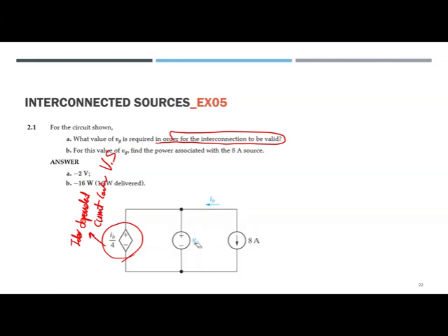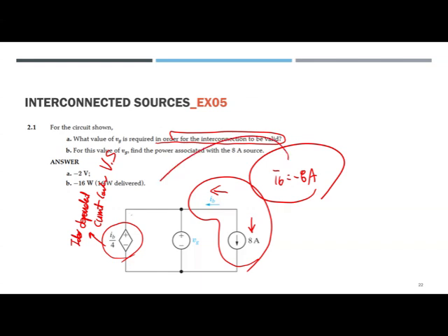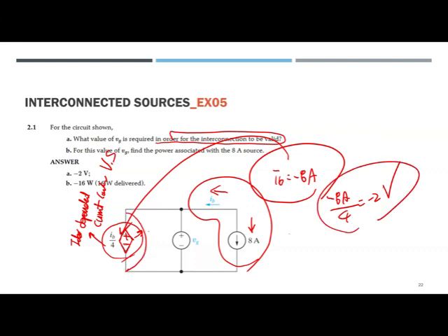Step one, that was the reverse direction. So I sub B right here is minus I sub A, and that was plugged in here. Oh, I'm sorry, minus the 2 voltage, because that was the ideal dependent voltage source. So this is minus the 2 volts, and that was also minus the 2 volts. They are in parallel, so they should be the same. So V sub G was minus 2 volts. That is the answer for 2.1a.